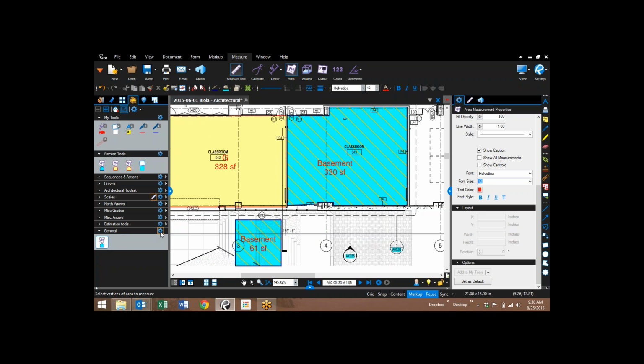Now, one more thing I like, so if we click on the general, this little gear right here, and then instead of symbol to detail, now it shows that little symbol, but now it says what the subject is. So here's where you really get into the takeoff workflow.